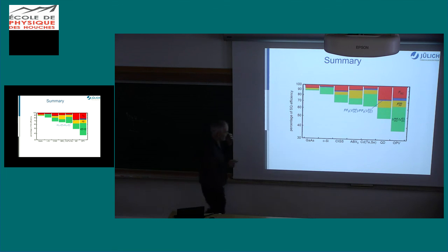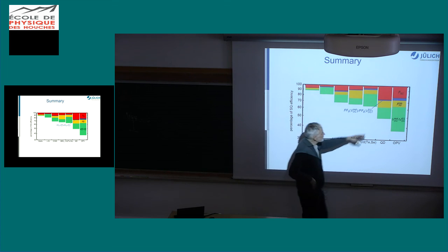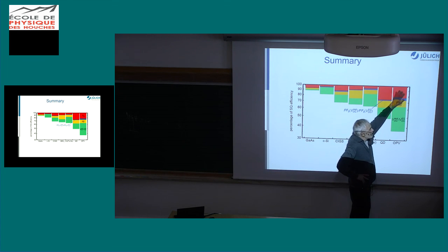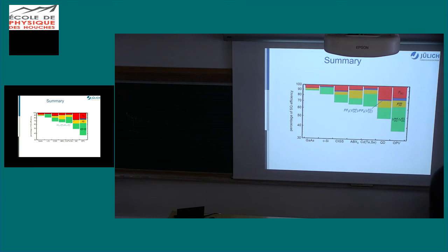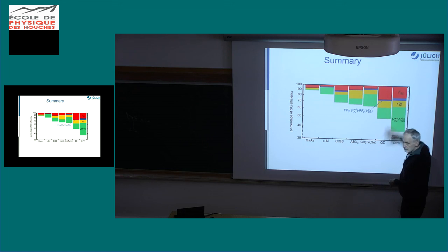And then we have four different losses. That's just the figure of merit short circuit current. That's the short circuit current that you're losing in your actual device with respect to the same Shockley-Queisser device. So that's something that's smaller than unity as a factor, and that's why it's negative here, going from 1 down on the log scale.